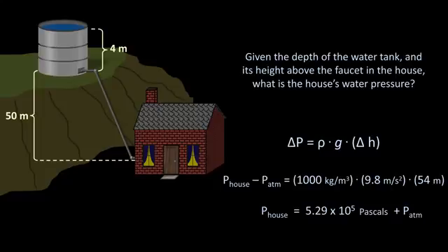In addition, this idea of a pressure that is equal to some number plus atmospheric pressure gave rise to the concept of gauge pressure, since atmospheric pressure is essentially equal at both the top and bottom of this type of system. The gauge pressure in this type of situation is the total pressure minus atmospheric pressure. When people refer to the term pressure in most everyday situations, such as discussing their home's water pressure, whether or not they realize it, the gauge pressure is often what they are actually referring to.